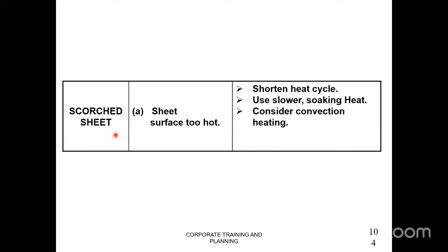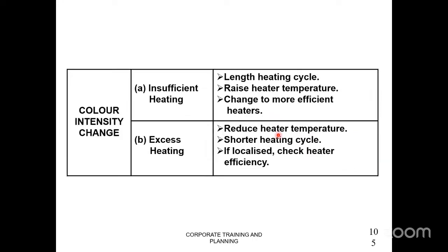Then scorched sheet. The sheet surface is too hot, right? And then scorching takes place, friend. Therefore, you have to shorten the heat cycle, use slower soaking heat, and consider convection heating, right?